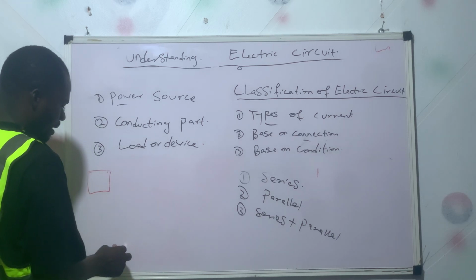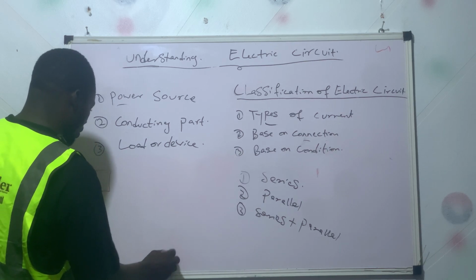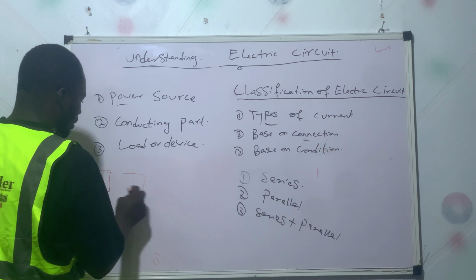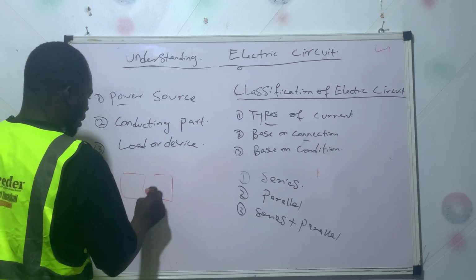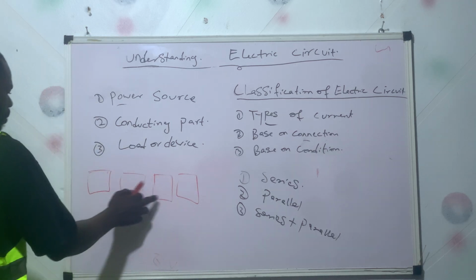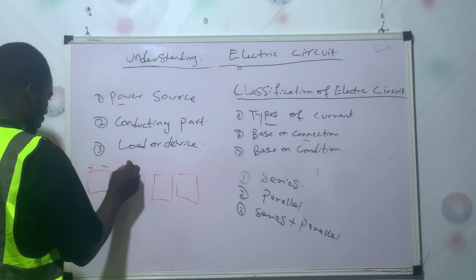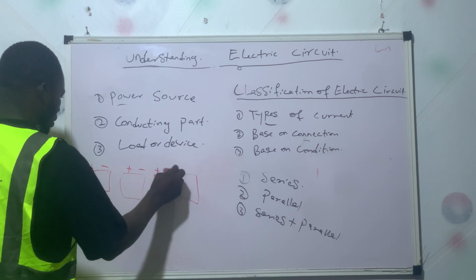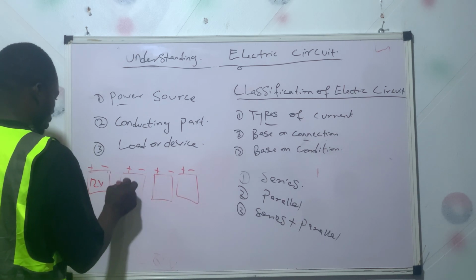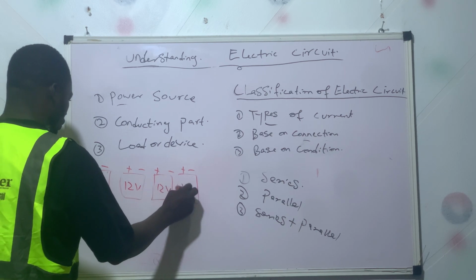Remember, we are connecting a 48 volts inverter system. Now this is the second battery, and we want to connect this in parallel, plus and minus, and they are 12 volts batteries.